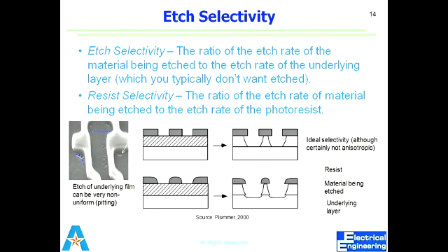So I have one question. If we etch away the substrate, that can be a problem for the device later. Of course, it depends upon your application. If in the design I don't want my substrate to be etched away, then that can create a problem for my device. In some applications, maybe it's not affected, but the point is that it's not giving you what you want. It's actually distorting my substrate as well; it's unwanted, undesirable etching that I don't need. But if you need it, then of course you can use some method.